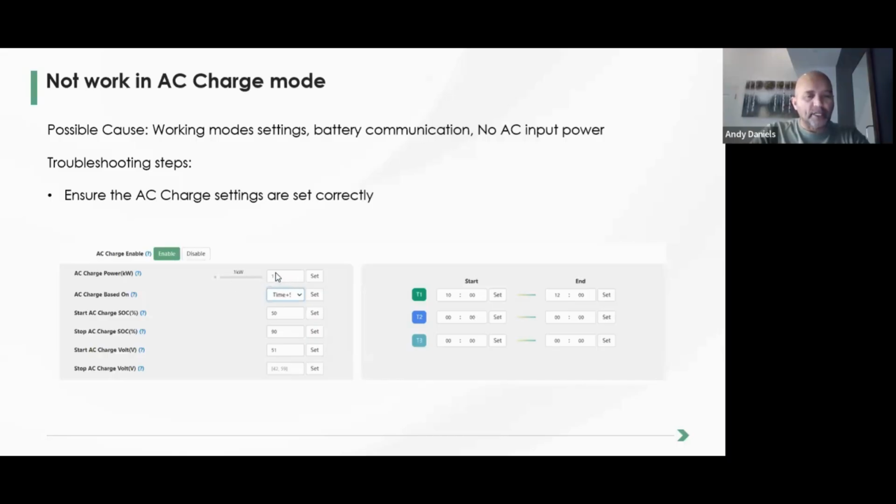There's two ways of doing it. You can type in the number here, the numeric, and set it, or you can simply grab the slider and slide it up and down here, and you can watch the value change. Very important, guys, in the maintenance page, I know a lot of you know this already. When you open up the maintenance page, right in the top, there's a read button. You have to click that first, okay? Because the settings page will be unpopulated.